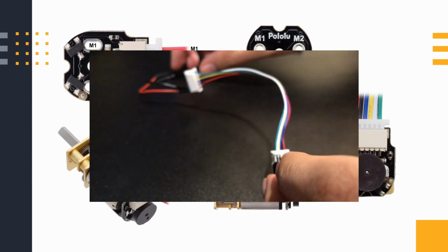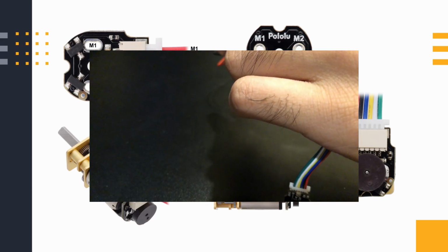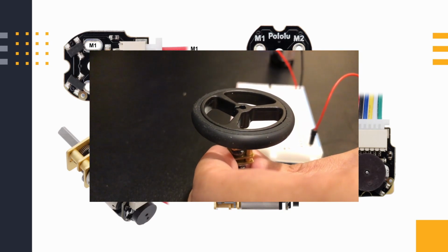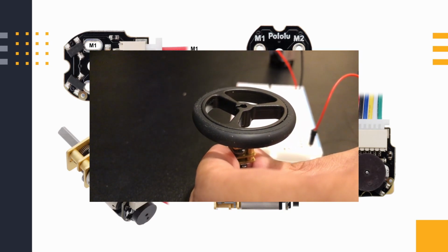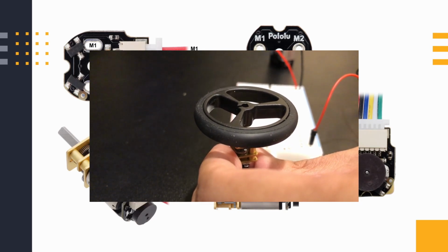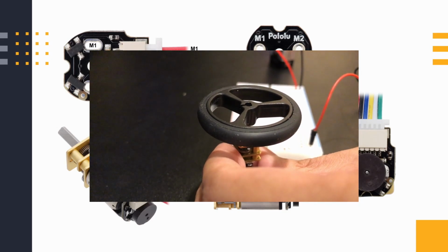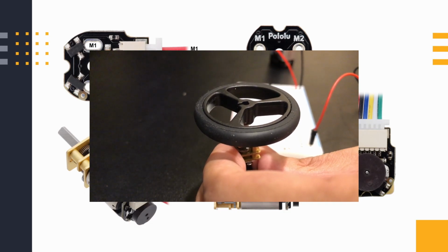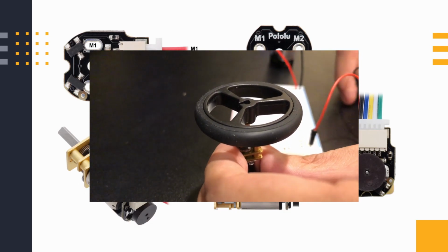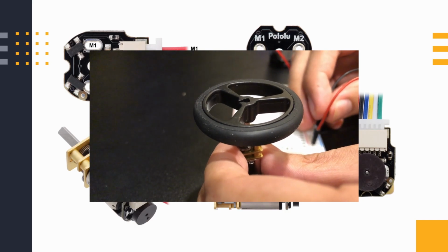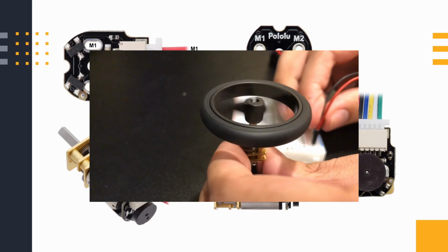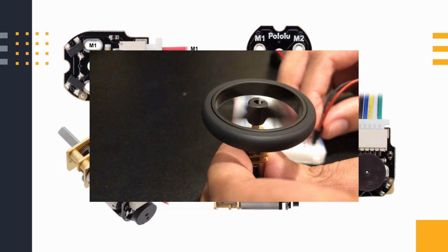So I'm going to attach M1 and M2 to a battery. Connect that. Okay, so if I do it like this, typically you shouldn't keep your motors on full power all the time. As I said, the brushes do come in contact with the commutator, and if you run them on full power all the time, those brushes are going to wear out. Again, these are decently good quality motors, so they won't wear out easily, but do keep it in moderation.